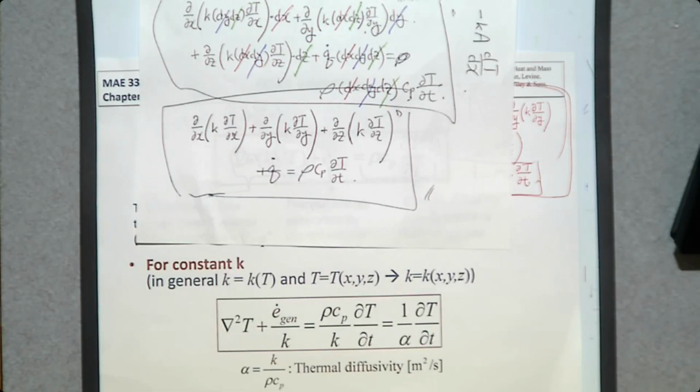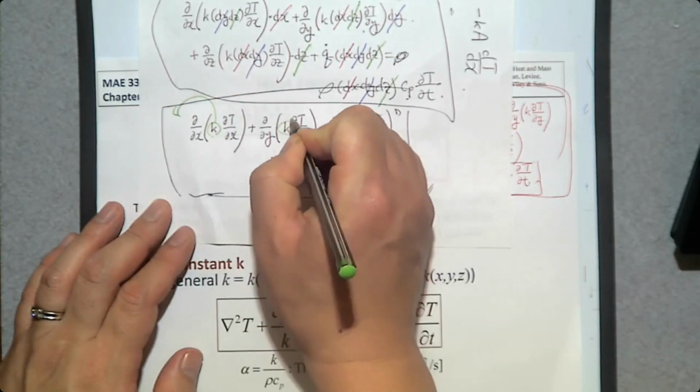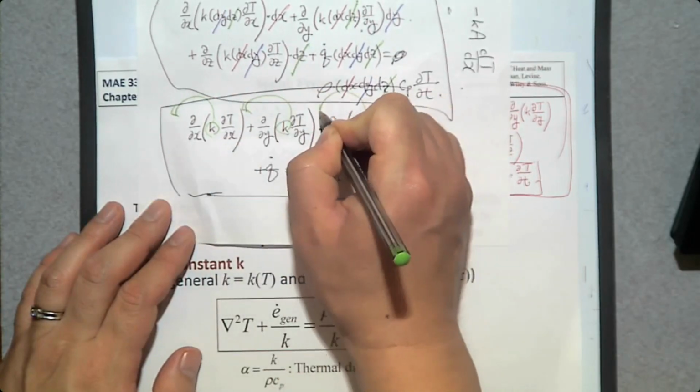Usually heat transfer takes place in a near temperature range. What about heat transfer from this classroom to the outside? Here is about 20 degrees Celsius. Outside minus 200 degrees Celsius? No, 10 degrees Celsius. How much k value change between here and outside? Not much. Then can we assume k constant? Yes. Then if you assume k constant, this k comes out, k comes out, k comes out.